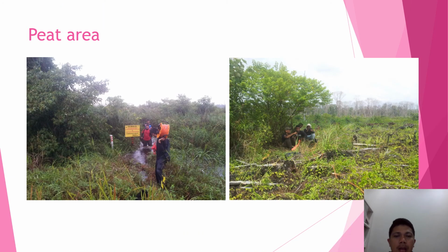And then the peat area also, for near surface, because normally in Malaysia, based on my experience, the peat thickness is normally less than 10 meters, so you can use the resistivity method to identify the thickness of peat. I was involved last time in several projects related to identifying peat thickness.